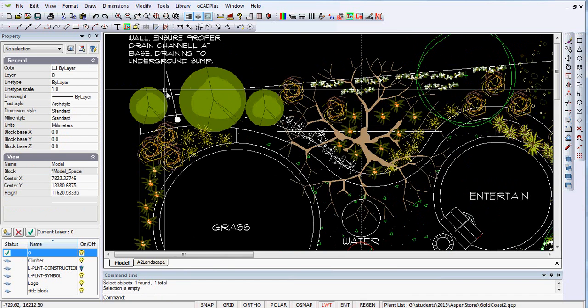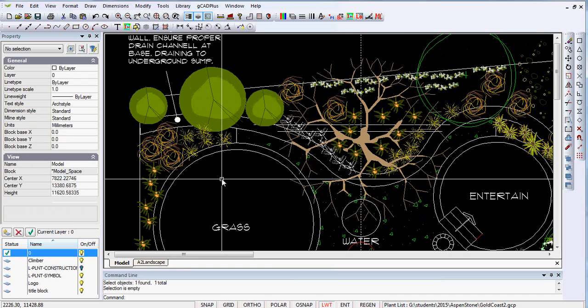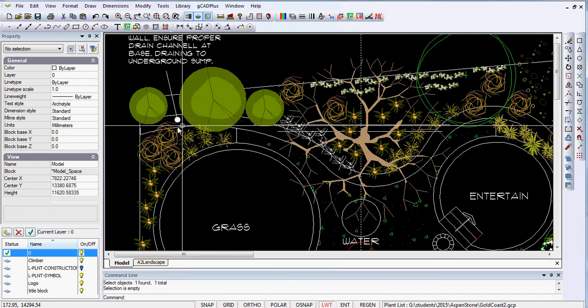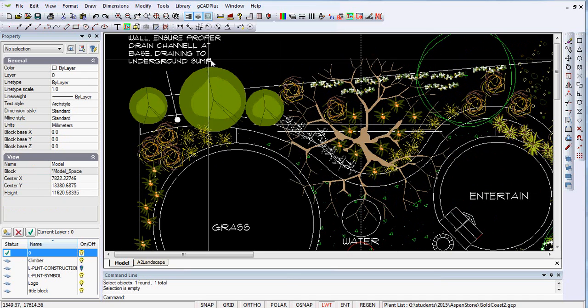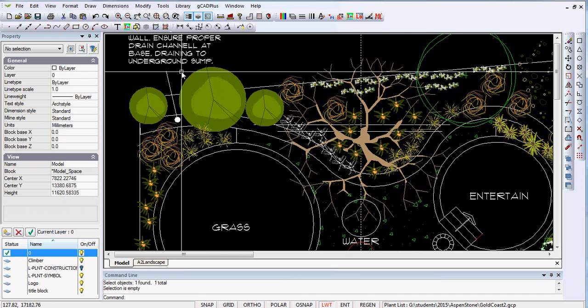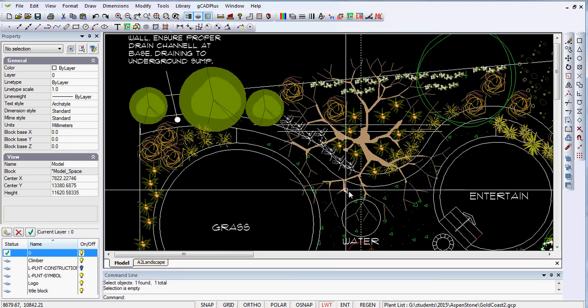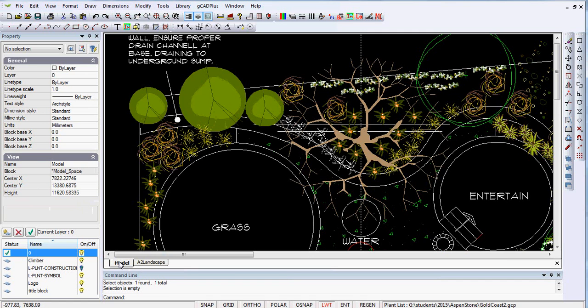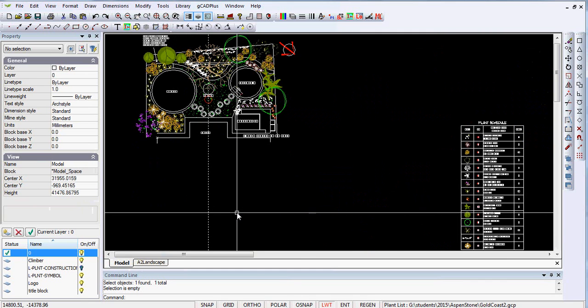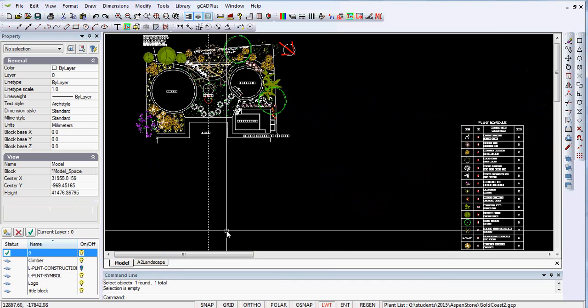Now we've got a nice little indicator indicating that wall. Although I'll show you later that you can hatch that to give a stone look, I prefer more detailed text descriptions of elements within a design. Coming back here, just making sure that everything sits the way we want it. And right click. Good idea to always leave your drawing zoomed extents when you close it.